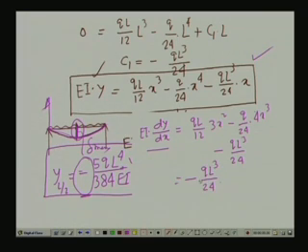Here, if you note, again this is negative. Now, this is the deflected curve as we have obtained. If we take the tangent of this elastic curve at this particular point, then the rotation is in the clockwise direction. As we have seen, in a beam segment the positive bending moment is in an anti-clockwise direction, and consequently, since this is clockwise, we say this theta is negative. Now, if we compute the rotation at the other end, at x equals L, let us substitute x as L in this expression and see what we get.